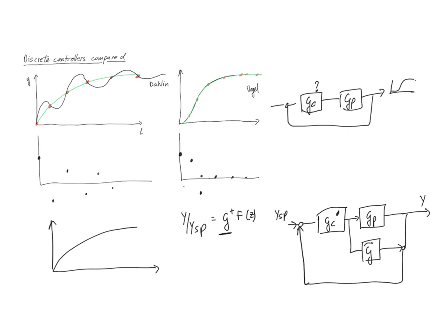What this allows us to see is that the undesirable parts are unstable poles that would become non-causal if we inverted them, as well as ringing poles, and then we can choose the filter so that this combination looks the way that we want it to look. So we can find some combination of the filter and the undesirable parts of the plant that will give us the behavior that we want. This allows us very clearly to see where we should accommodate the undesirable parts of the plant, and it allows us clearly to make decisions where in the other prototypical approaches we kind of had to guess.